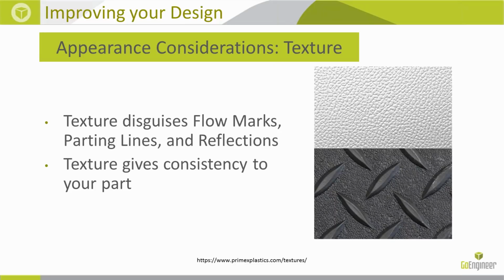One thing that you do want to take into consideration is the appearance. Texture disguises some of these manufacturing byproducts, so to speak, like flow marks, parting lines, reflections. So texture kind of helps you in that way. And you need at least a minimal amount of texture.